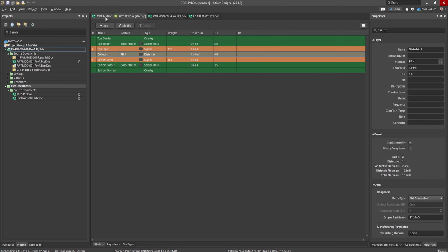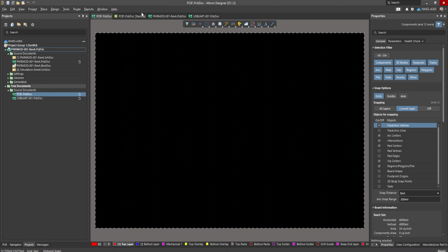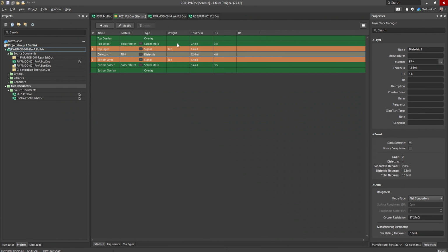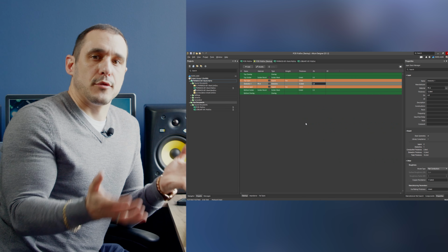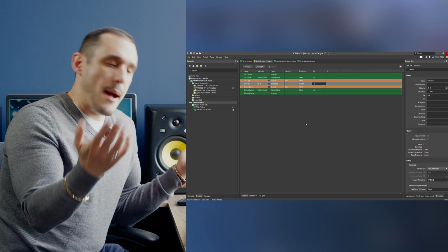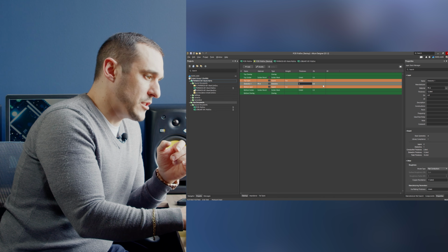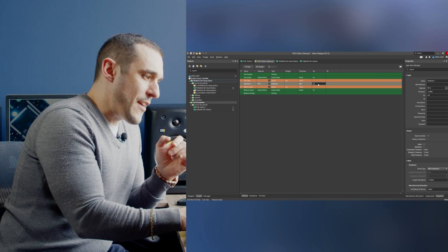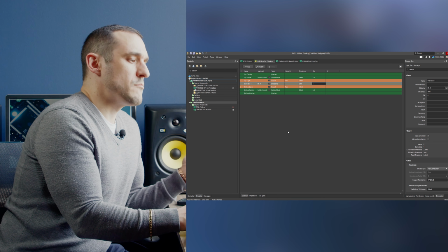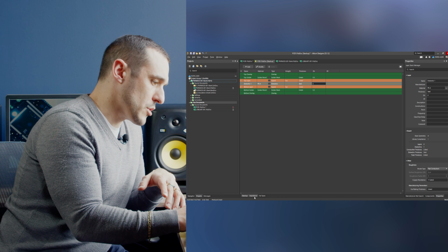So here I have a blank board, and in this blank board, as I usually do, I've just set up a basic stackup, and we're just going to pick a Dk and a thickness value for this dielectric, and then we're going to see what happens to the impedance. So I'm going to consider, just for fun, let's say a 5 mil dielectric, and then a Dk value of 4. So pretty typical for thin dielectrics.